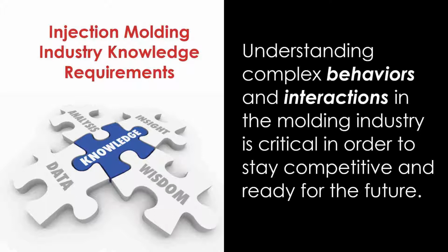Understanding the critical components in injection molding is really important before you try to optimize a part design, because only if a part design is optimized should you go into the mold design. The mold designer then needs to do their magic to optimize the mold design, and when those two functions are done, only then should you build the tool. And then when the processor gets the tool into the machine, it will probably have a very wide molding window.